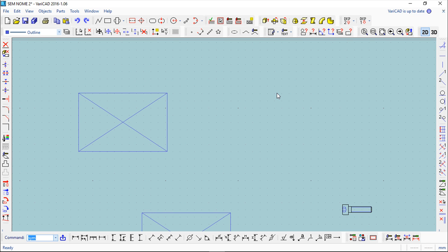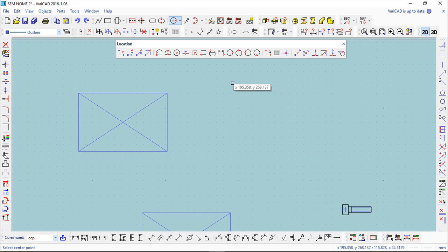And now talking about the blocks, you can say, oh, blocks are quite similar to symbols. Yes, in fact, it's more or less true, because symbols are, in my opinion, a little more flexible, because of this concept of the libraries. In terms of the blocks, you will save a couple of entities inside a file and that's it. It's not so flexible, but I will show you anyway how to work with it. So I will create some new geometry to test with the blocks.